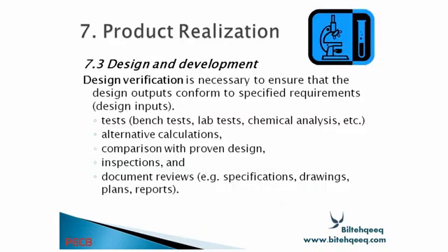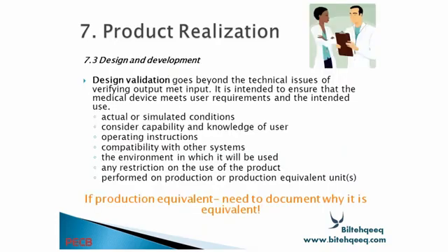And now we will talk about design verification. Design verification is necessary to ensure that design outputs conform to the specific requirements. Methods include design input test, bench test, lab test, chemical analysis, etc., alternative calculation, comparison with proven design, inspections, document review, for example, specification drawings, plans and reports.